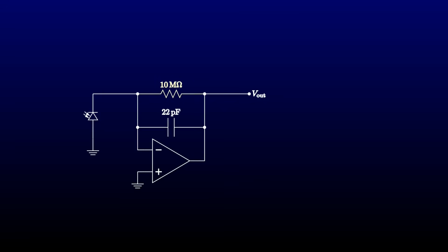I really don't like using a 10 megaohm feedback resistor. The op-amp will have some small bias current, and that small bias current will be multiplied by the transresistance and can add up to a significant voltage. What's worse, the bias current will be horribly temperature dependent. Also, that 10 megaohm resistor will contribute quite a lot of Johnson noise. But fortunately, I'm not using just a photodiode. My diode is the base collector junction of a phototransistor.